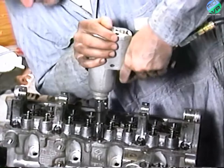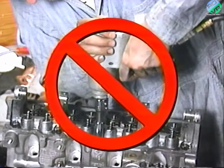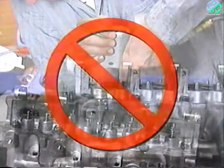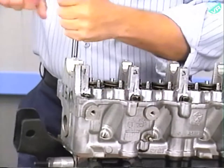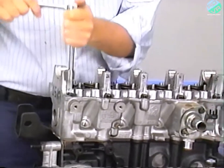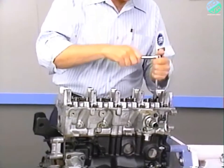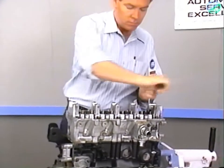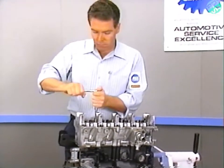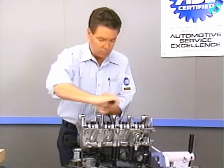To avoid damaging threads, never use an impact wrench to install or remove cylinder head bolts. This is especially true on engines with aluminum blocks or heads. Always use hand tools to install and remove cylinder head bolts. Also, to avoid warpage, the engine should be cold before the cylinder head is removed. Cylinder head bolts should be removed in steps, following the reverse order of the tightening sequence to prevent warpage.